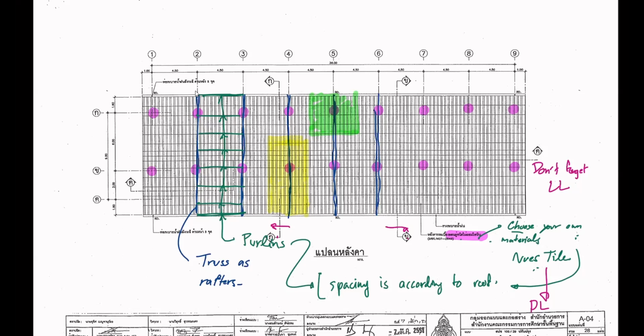Excuse me. Yep. Let you draw it. Let you write. Don't forget live load. So in the roof system, let's mention that the wind load will be negligible in this case, because it's not a tall building, right? But we're going to consider the workers, the people who work on the roof. That is covered in the live load. That is part of the live load. You have to. It's a live load.